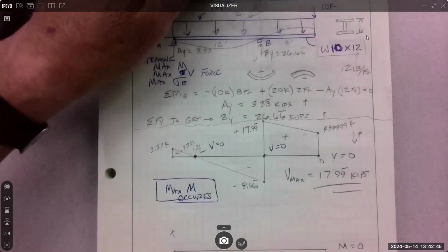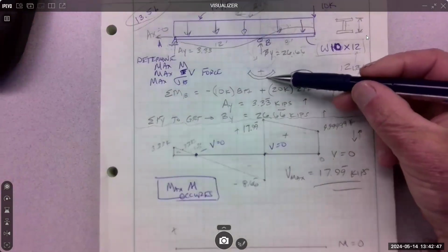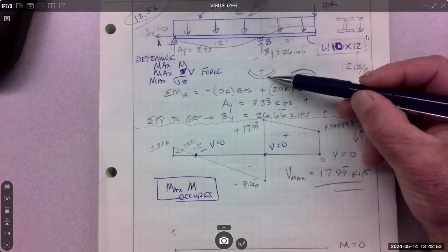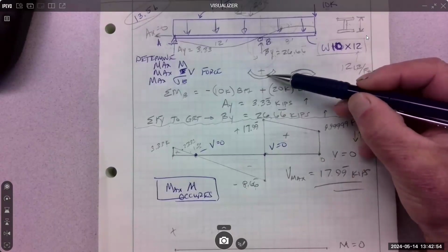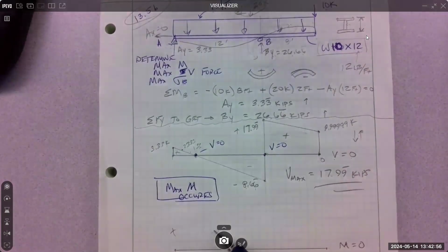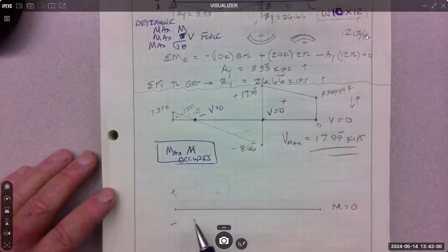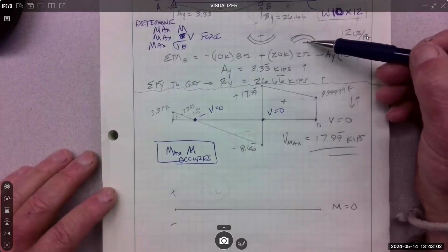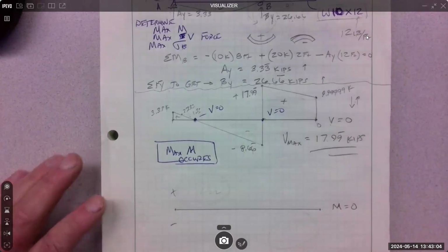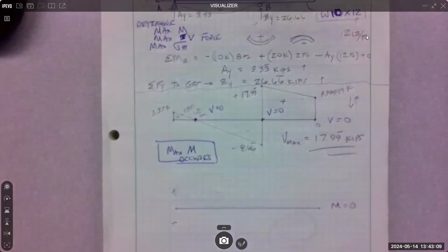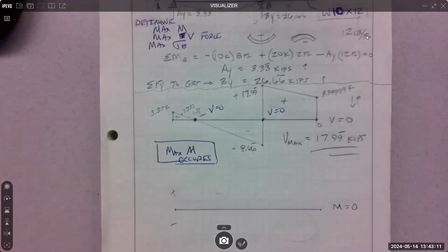So it's the rule. If the beam deflection concavity is up like this, it's positive moment, which means positive in the graph. If it's concave down, it's negative. So we're looking for the graph here and here, based on the elastic curve. It's not always easy to see the elastic curve, so it's just one of the clues.